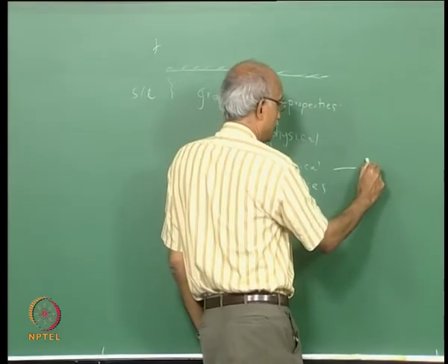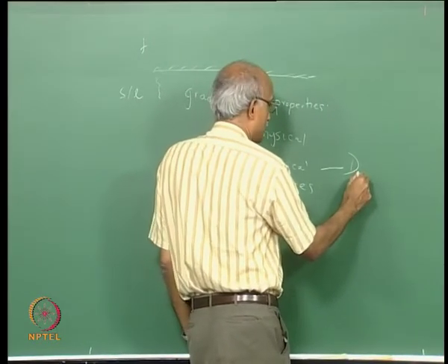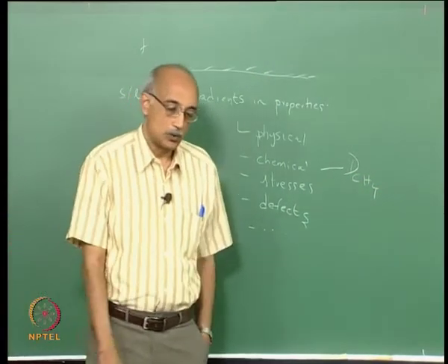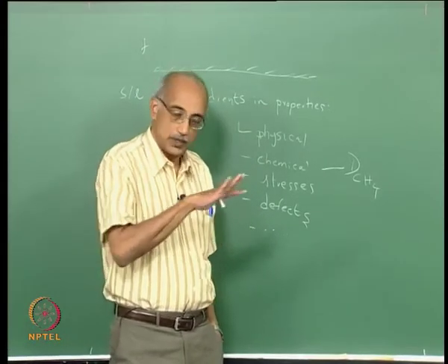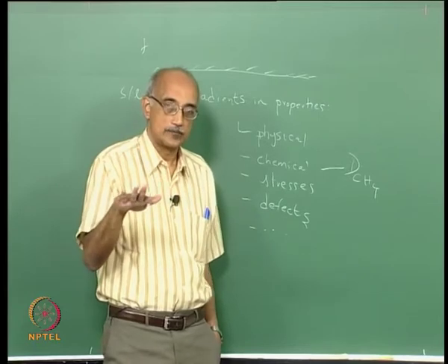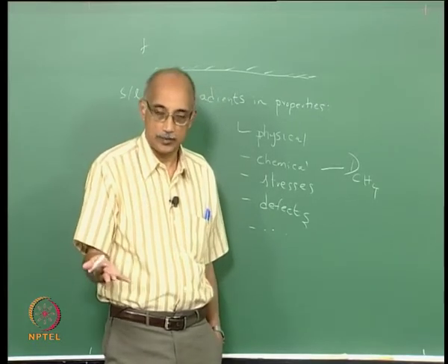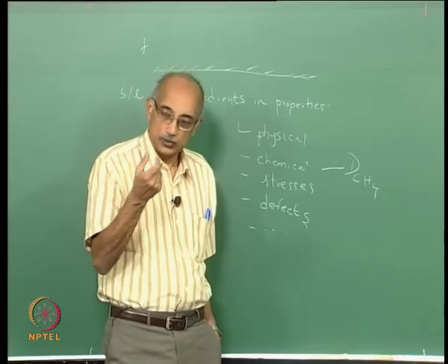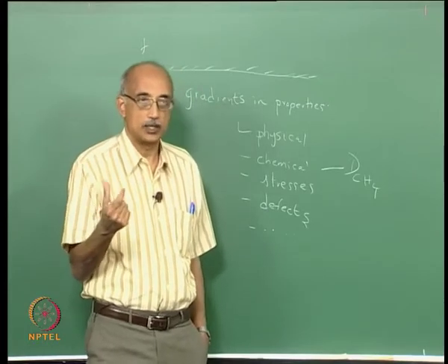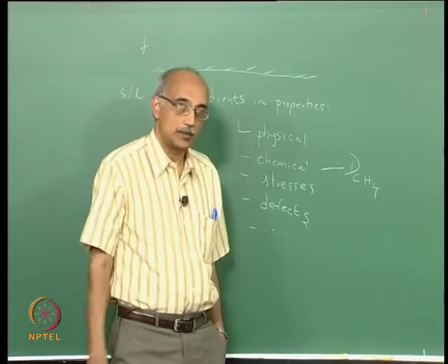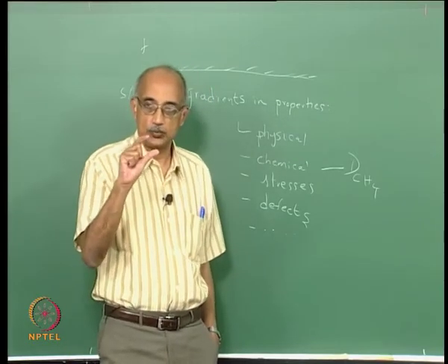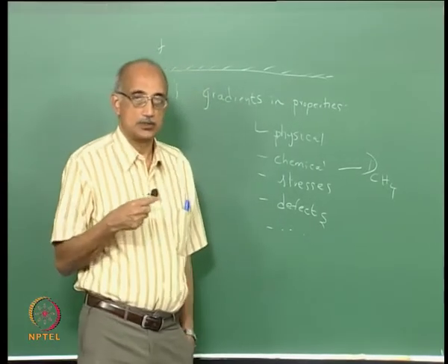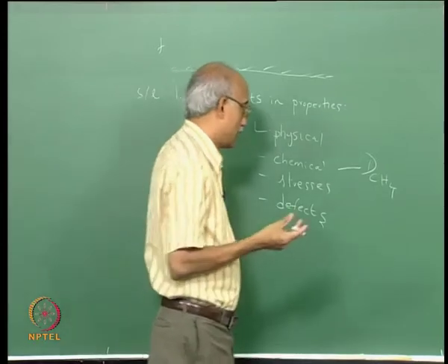So, what would happen is this species will diffuse with some diffusivity. So, let us say that you are using methane to achieve this carburization. This CH4 will essentially first encounter the surface of the alloy and it will leave behind carbon and therefore increase the carbon content. But then by controlling the amount of diffusion of this carbon containing species into the matrix of the material, you can control the depth to which this carburization happens, because the distance that this species will travel within a certain time can actually be calculated.